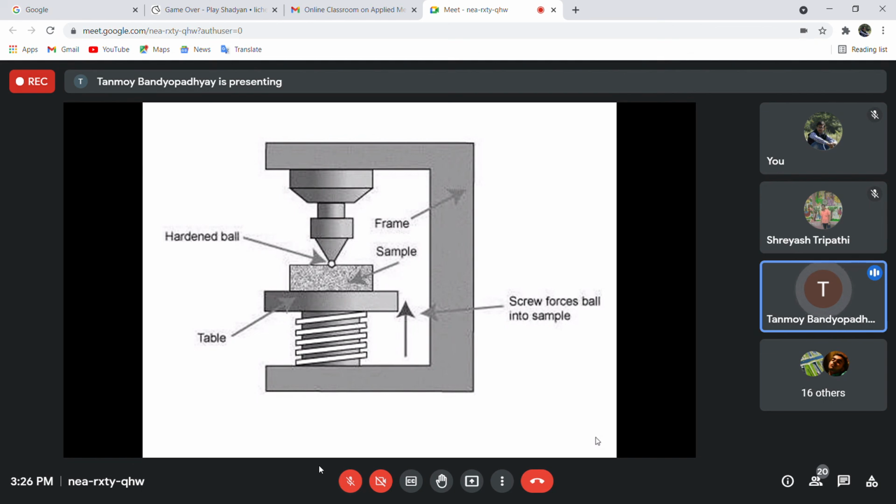These are not something that I can define. These are standardized with the machine setup. The machine manufacturers give you a manual, fitted on the body of the machine itself. There you will find what is the specimen type, and for that specimen type, what is the indenter that you have to use, and what is the load combination that you have to adopt. These are something that you have to always maintain.